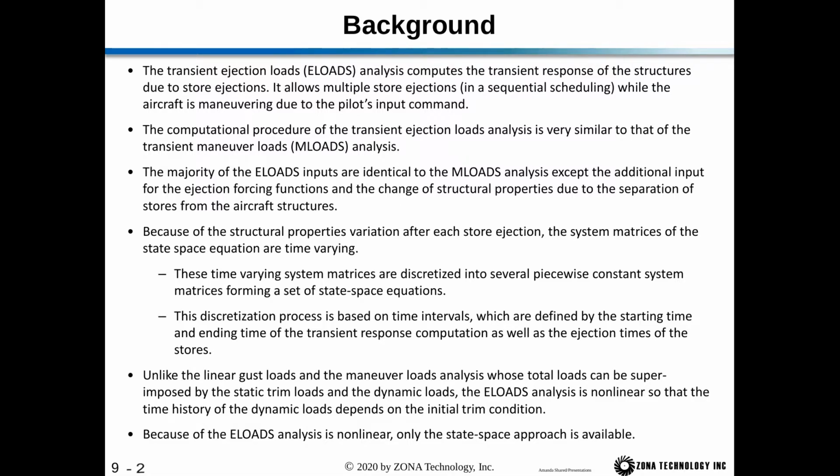The computational procedure of the transient ejection load analysis is very similar to that of the transient maneuver load analysis. And the majority of the ejection loads inputs are identical to the maneuver loads analysis, except we have the additional input for the ejection forcing functions and the change of the structural properties due to the separation of stores from the aircraft structures.